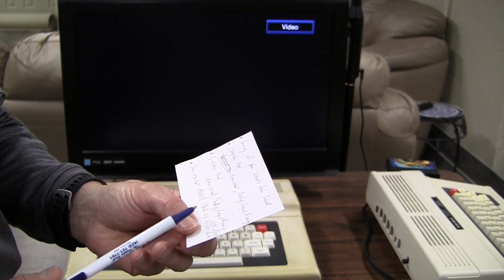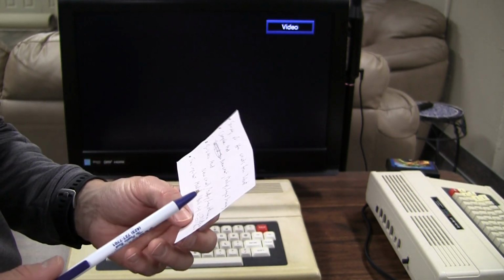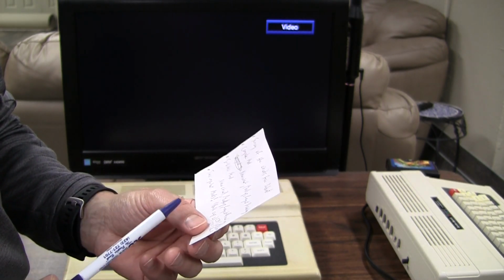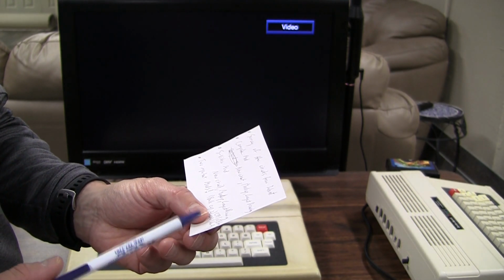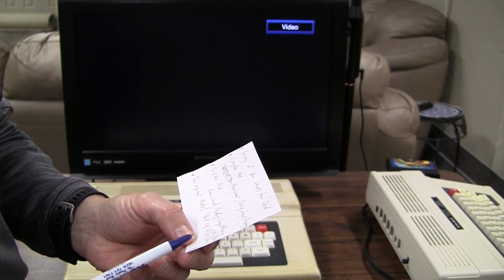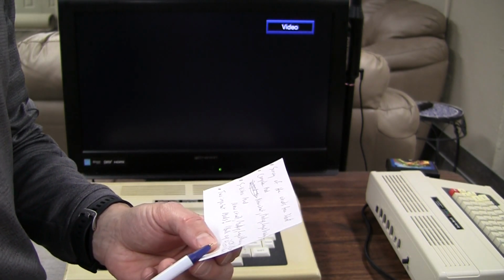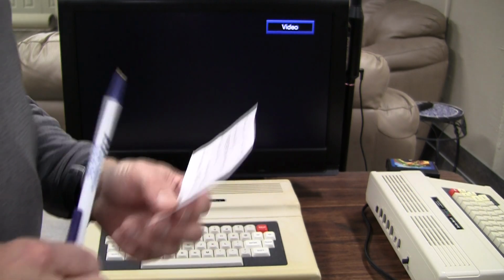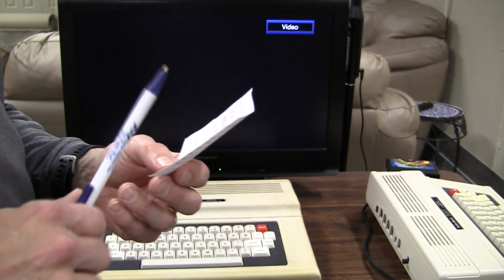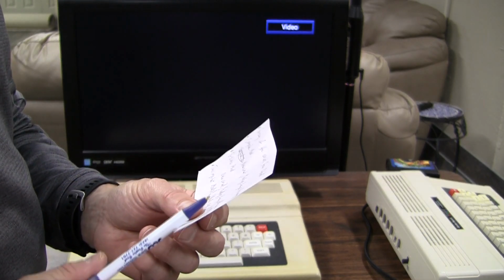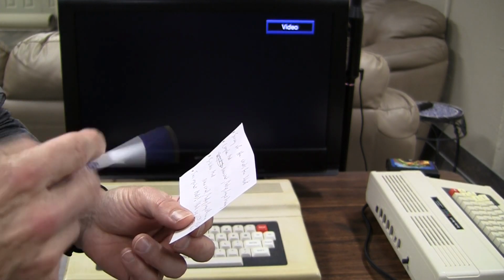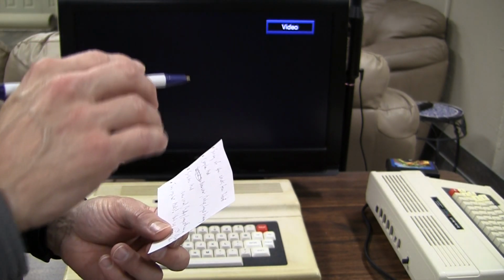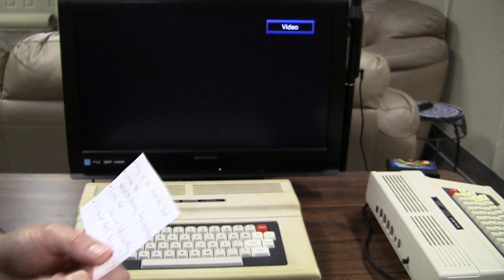And 2, I mentioned it earlier, but there's a small 150 picofarad capacitor on the luminance line on the main board of the CoCo 2. On the old board, it's C59. On the newer Rev A board, it's C23. It's not critical and not required by any means, but I just noticed slightly improved luminance quality when I removed that capacitor. It just slightly sharpened the edges of the waveform of the luminance pulse, so that it's not filtered and rounded off as much as it was before.